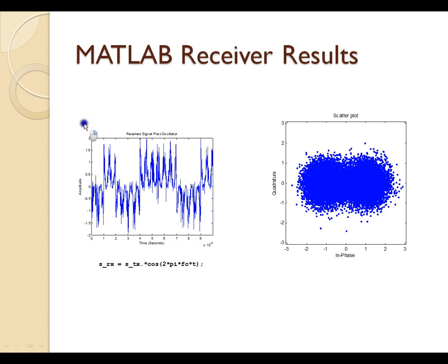Of course we had to demod from the RF frequency to the baseband frequency first, and after the demod we get this signal right here. And then the constellation diagram of the left plot is this. As you can see, you can't really distinguish between a phase of 0 and a phase of 180 here, because they're all mixed together. So that's where the integrate and dump filter and all that stuff comes into play in the next slide. Here is a demod: you multiply to get the frequency and you bandpass it, so you get the baseband frequency.